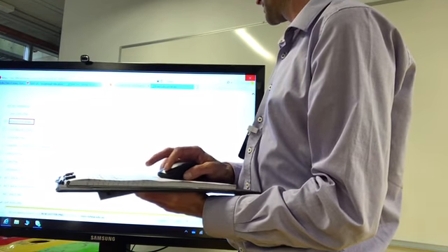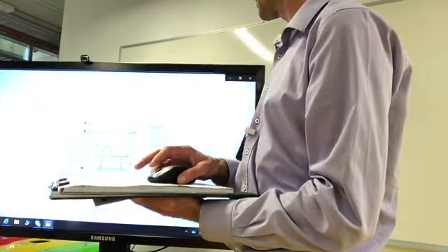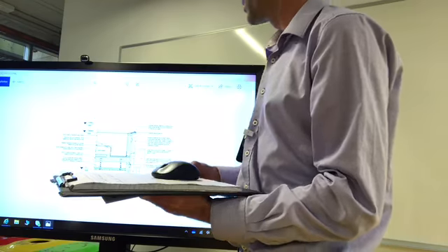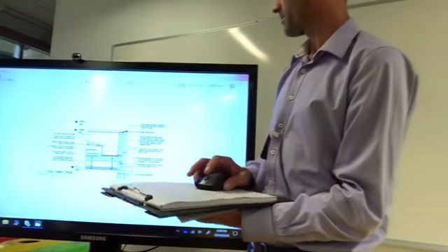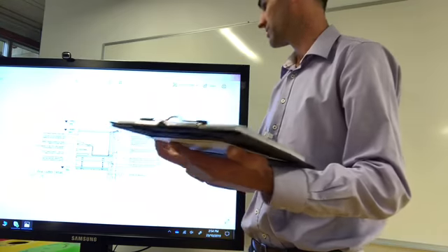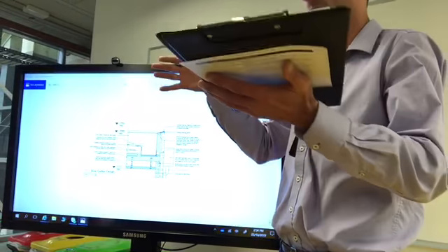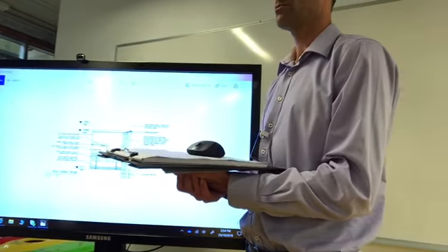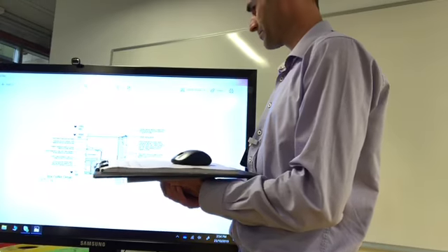For your box gutter detail, however we do it, we're going to be dealing with a parapet. We're going to neaten up the building and help hide surfaces and things like that. You want to carry parapets past the roof line of the building.